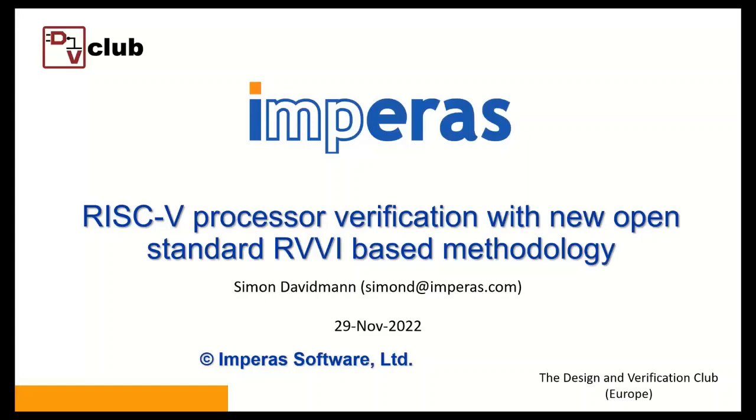So the first thing you need to do is work out what level of DV you want to do, and then create a tracer which gets the information out of your RTL into the test bench, and then pick up components that can use RVVI. One of the first things that we're making available as Imperas as open source is what we call RISC-V ISA coverage, which is SystemVerilog source files for RISC-V functional coverage, which will just plug on top of the RVVI interface and, as you're running your simulations, give you functional coverage. But obviously, that requires a SystemVerilog simulator that has cover points and cover groups.